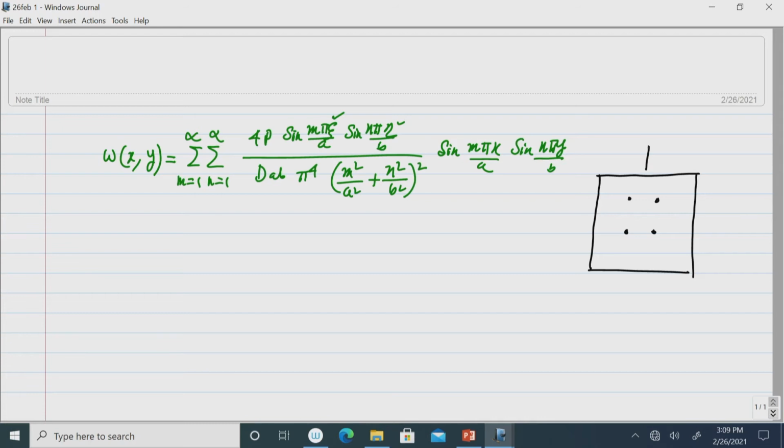So, wheel loads are imposed and you can see if this is say P 1 in the same axle, of course, the load is same, then P 2 P 2. So, if this is the direction of motion, you will see that the load imposed on the plate is a concentrated load and it is a moving load. So, concentrated load formulation is very important especially for bridge deck analysis when the wheel loads are treated as a concentrated load. The expression for W is found out and based on which we can find out the expression